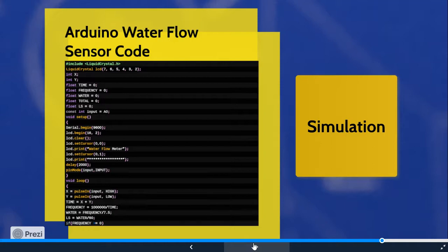And if the output valve of the pipe is open, the water runs via the sensor, which makes it revolve. In this situation, we can see pulses which are produced from the sensor. These pulses basically will work as the interrupt signal of the Arduino Uno.